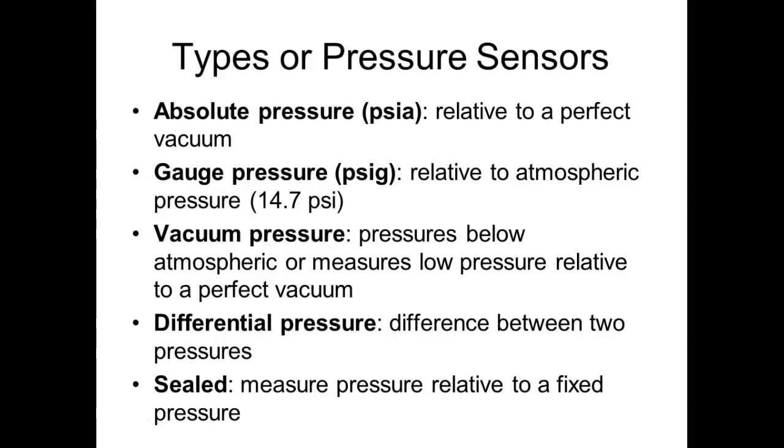So if I had an absolute pressure gauge in here and I was holding it in my hand right here, it would be showing 14.7 psi. Because when we say 14.7 psi, where does that react on? That reacts on all surfaces, on all different angles. So right now, where do I have 14.7 psi? I have it on the bottom of this chair, on the side of this chair, on me, on my head. So pressure is at right angles on anything.